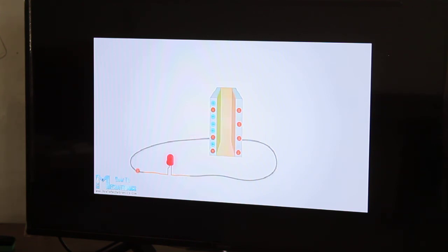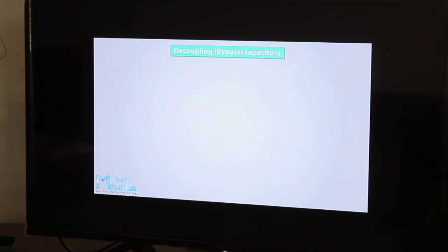Signal filtering is another application example of capacitors. Because of their specific response time, they are able to block low frequency signals, while allowing higher frequencies to pass through. This is used in radio receivers for tuning out undesired frequencies, and in crossover circuits inside speakers for separating the low frequencies for the subwoofer and the higher frequencies for the tweeter.